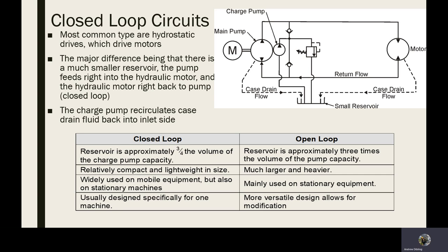Same thing with your main pump here, and this is an electrically driven machine. You have a charge pump here. This charge pump would charge the system prior to its running, and once it's charged up, this line will come open. When this charges up, eventually the pilot line will send some fluid down if it gets too high to the spring pressure and return the flow, dropping the flow back on this. But in the meantime, this flow will push out of these check valves.